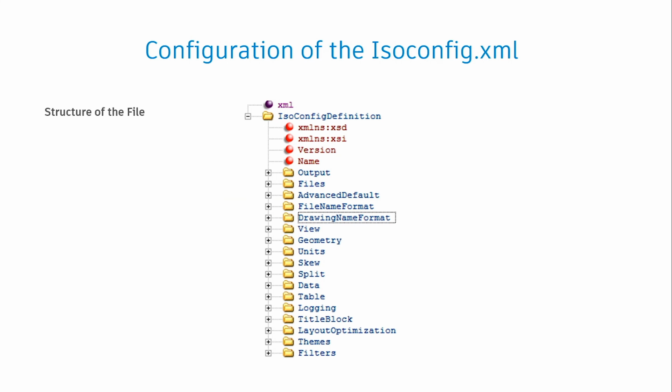There are the following override themes: small bore piping, fitting to fitting, vent drain piping, offline instrument connection, existing piping, continuation and connection piping. The main settings for these override themes are about dimensions and annotations.